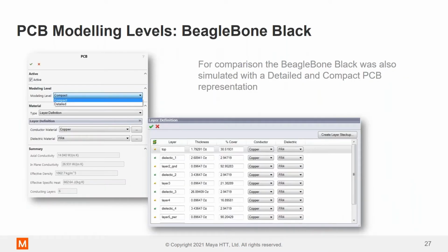Okay, so you don't have to model it in that higher detail, especially if you're early on in the design phase. Maybe you don't have that level of resolution. The PCB team haven't laid out their boards or finished routing them even. So we can also model the PCB as compact or detailed. And I'll get onto this, but basically we can either do a volume averaging of copper within the PCB for the entire board, or we can do it on a layer by layer basis.